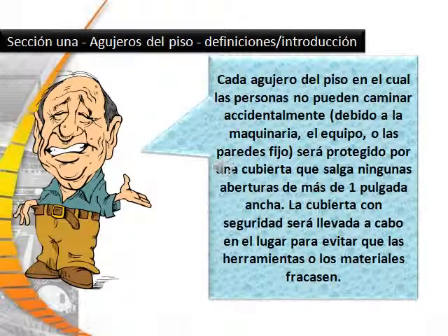Remember, every floor hole into which a person cannot accidentally walk because of fixed machinery, equipment, or walls shall be protected with a cover that leaves no openings more than 1 inch wide. The cover shall be securely held in place to prevent tools or materials falling through.